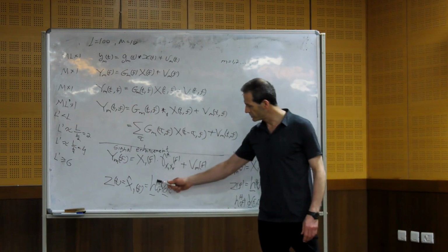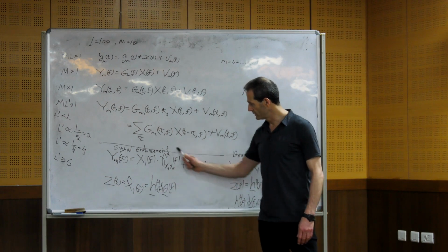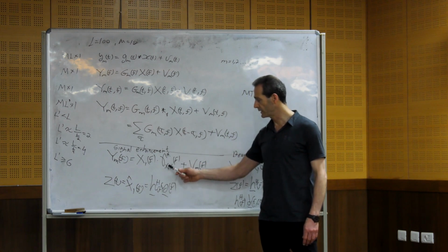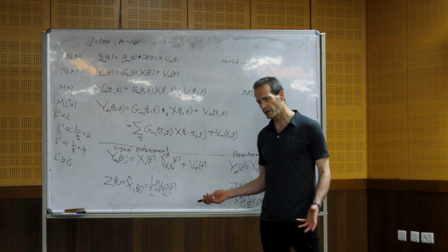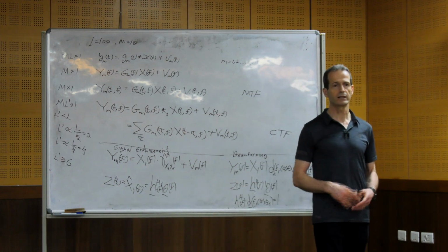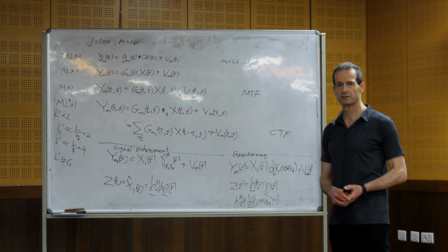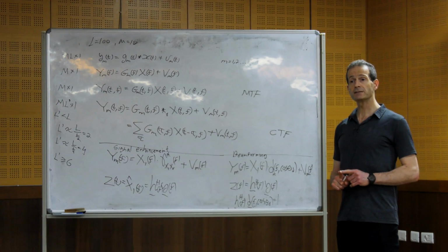So H that is applied to the vector of the relative transfer functions, we require that it will be 1 if we want to work with MVDR or LCMV or GSC, just like we saw that it's equivalent. Any questions?